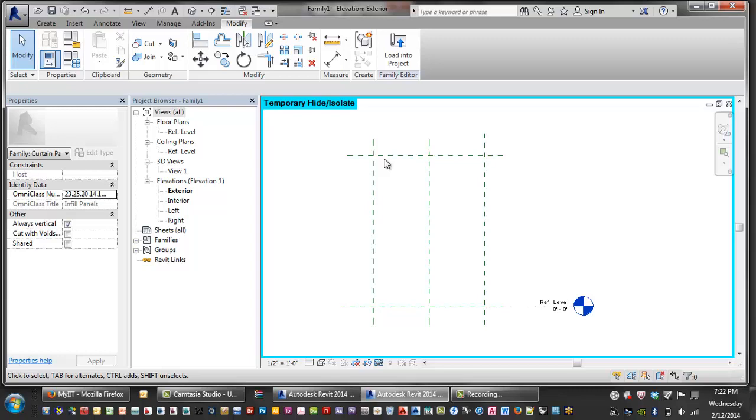I can either make this entirely operable, or I can cut this in half and make just this part operable, because you need to get ventilation. And then I'm going to load in another slab edge cover. And what we'll do is put a visibility parameter on each one of those slab edge covers, depending on where it gets loaded in the project.